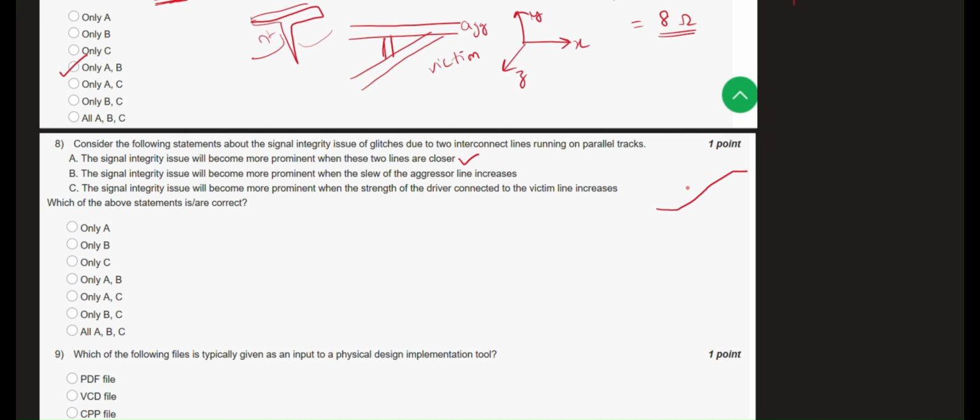I mean it is not rising abruptly. And if the signal line is increasing slowly, then the charge deposition on the coupling capacitor between the two wires that are going to crosstalk will be slow, and the voltage developed across the capacitor will be slow. It means there is less load on the driver gate to provide the charge to this capacitor. So I am not going to see the bump in the victim line, right? So that is the whole idea.